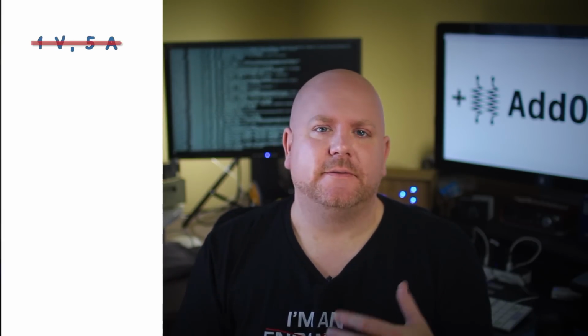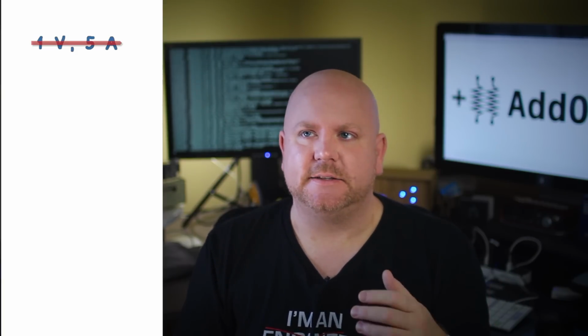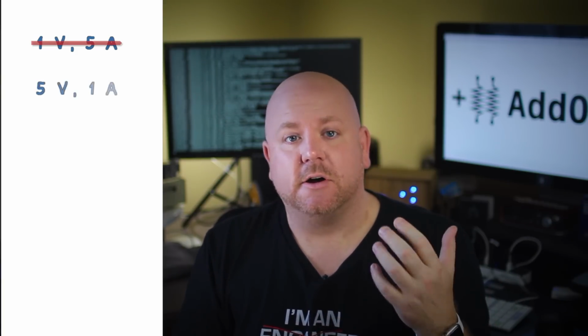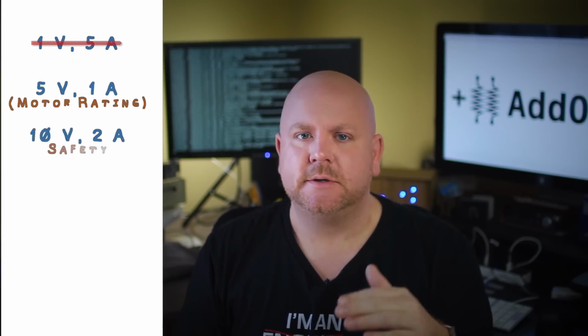So when I'm picking a diode, the first thing I do is look at the motor, which in this case, let's say it's a 5 volt motor that draws 1 amp. Because of that field collapsing and the timing of the collapse, you might end up seeing twice whatever was actually used. And so I immediately double those numbers. So I say 2 amps, 10 volts.